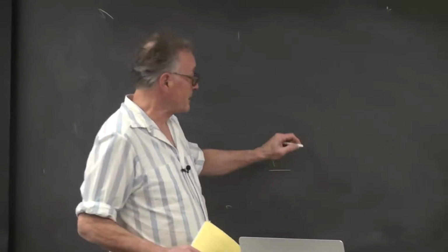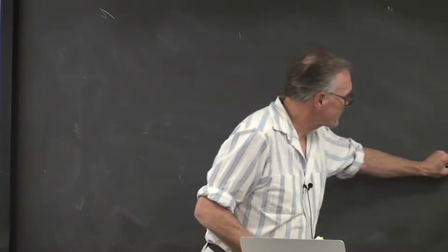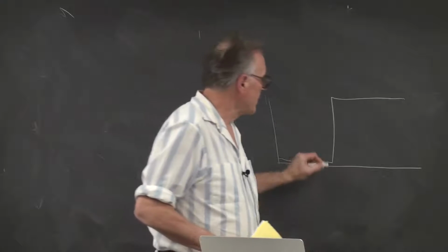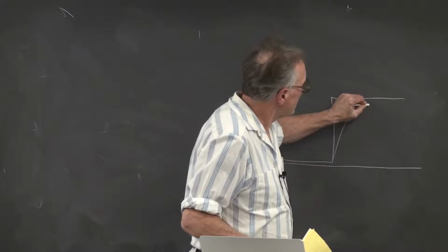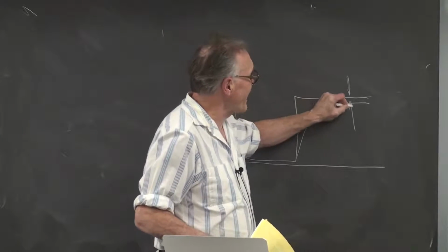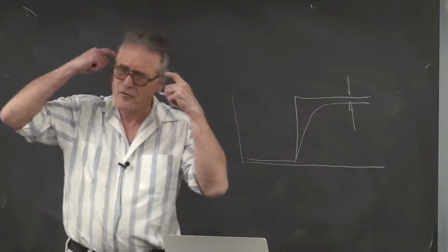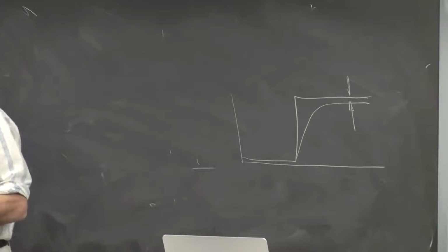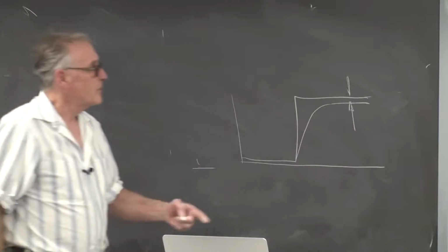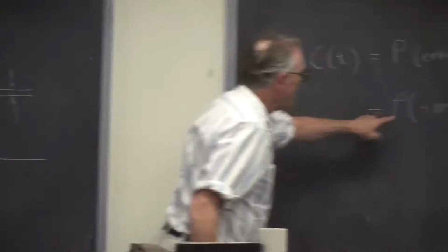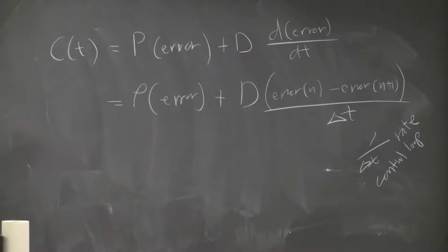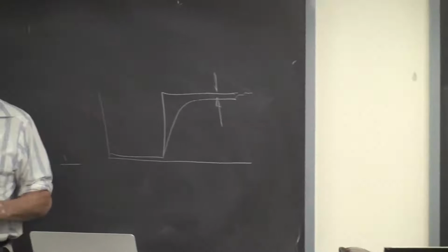Another possibility is, now thinking sort of in the time domain, you've stepped the system, you have a constant error which is related to the gain. Is there a way of changing the controller even more so that the static gain isn't changed, P isn't changed, but this system notices that it has a little error and sort of incrementally gets closer to the right value through a different scheme?